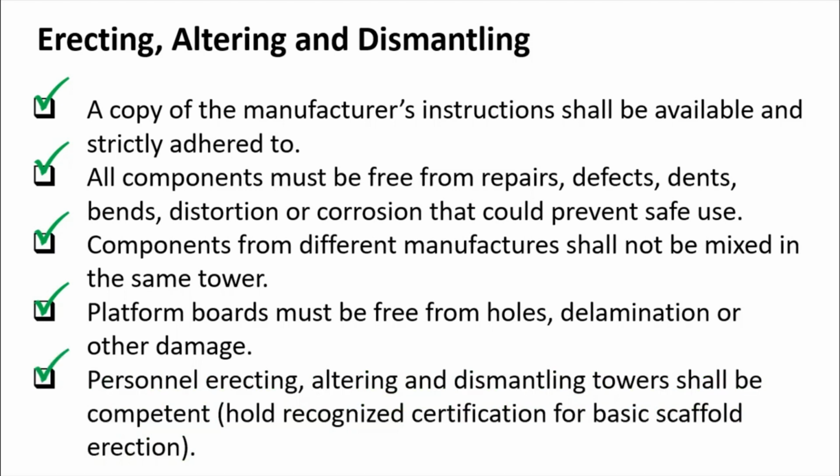Personnel erecting, altering, and dismantling towers shall be competent. So make sure that the persons engaged in the scaffolding works, scaffolding towers, are competent. Competent in the way that they hold recognized certification from the authority on basic scaffold erection, alteration, and dismantling.